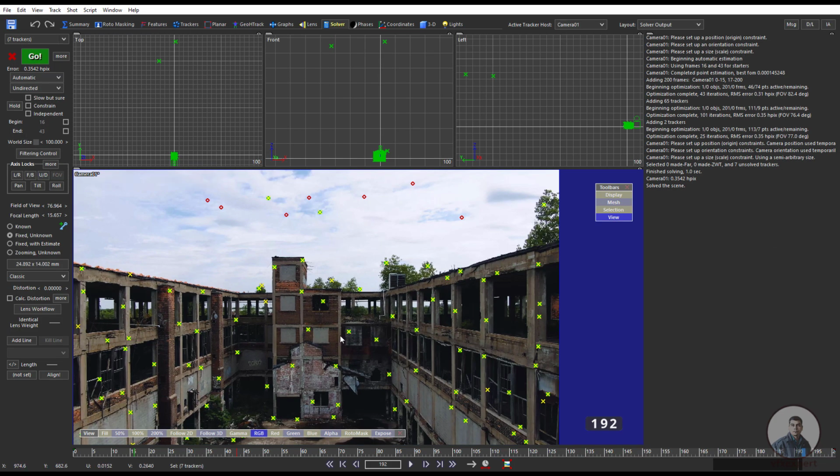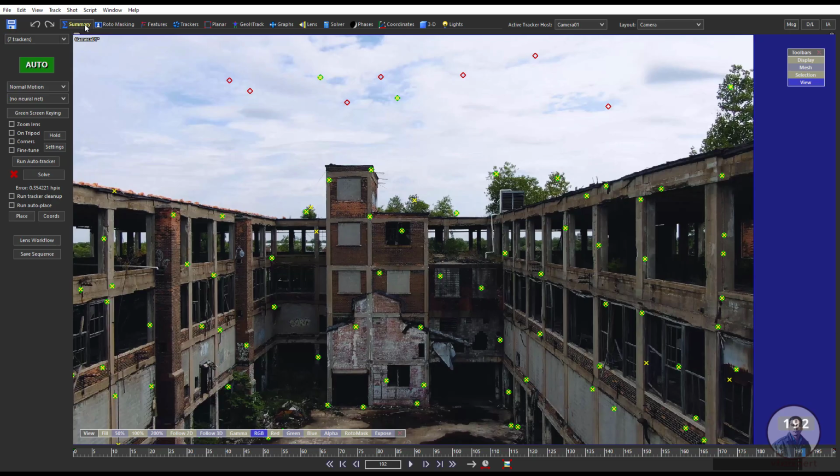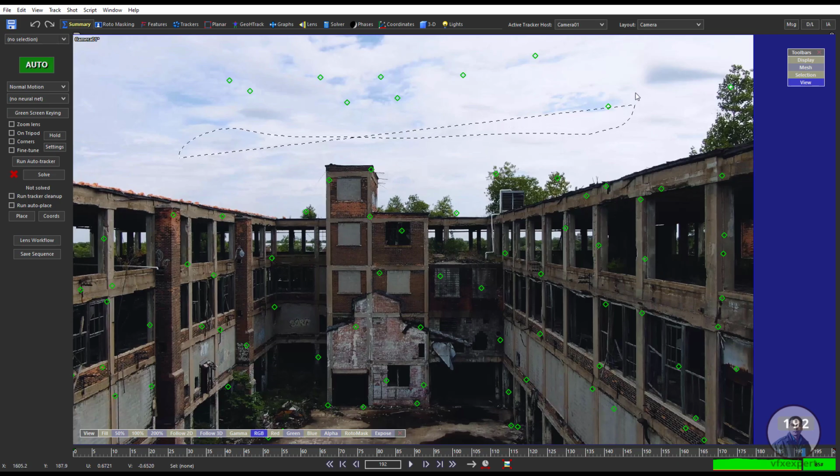Now again I am getting this camera solve here, and on the left side I am getting the camera error, which is 0.35. Now again clear this camera solve. From here you can clear it, or again come inside the summary tab and clear from there. So now, before solving our camera, I am going to delete all these high-error track points. Manually you can select these track points with the lasso tool and press Delete, and delete all these high-error points.